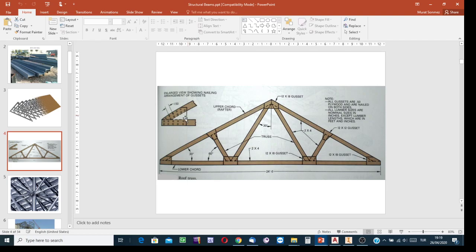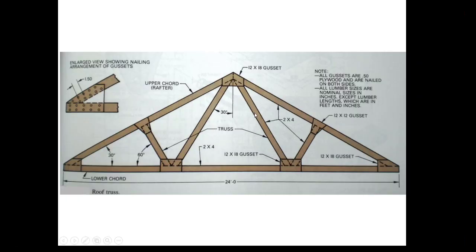Well, here, as the difficulty, I want to draw the attention. Think about it. You need to create the model of such a structure. And then think about this joint, this member, to its inclination, its end is to be finished with an inclined surface. Calculate its inclination angle. It's a trigonometry problem, knowing the inclination angle of this member, the inclination angle of the other members.